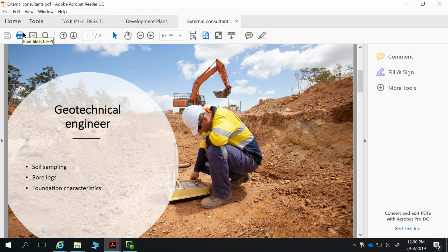So although we've got this cut off at 3 or 3.5 meters, I can't remember which, typically your geotechnical engineer is going to make the assessment that we've got to go down to a particular depth because we've got deep-seated clays in South Australia. The other reason they might want to go deep is to see how far those clays extend to work out reactivity.